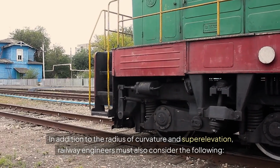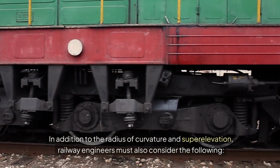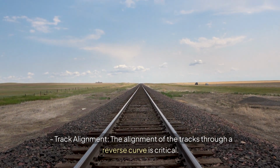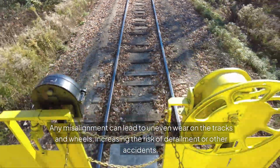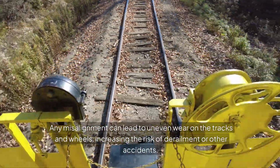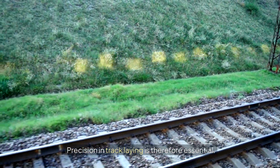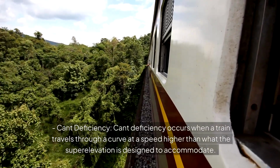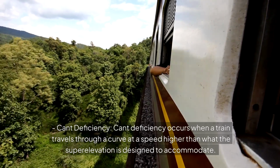In addition to the radius of curvature and superelevation, railway engineers must also consider the following. Track alignment. The alignment of the tracks through a reverse curve is critical. Any misalignment can lead to uneven wear on the tracks and wheels, increasing the risk of derailment or other accidents. Precision in track laying is therefore essential. Cant deficiency. Cant deficiency occurs when a train travels through a curve at a speed higher than what the superelevation is designed to accommodate.